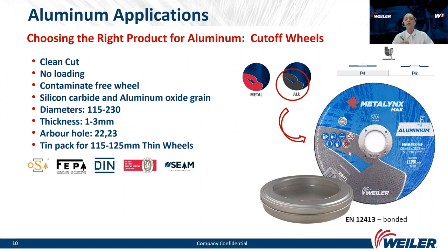Why is aluminum so different? It is softer and it has a lower melting point, and that's why it starts to clog. So it sticks on the product and the product stops working. So that's why we developed special recipes with special additives to prevent this from happening. So there is no more need to use waxes and also other chemicals to clean all that up at the end.